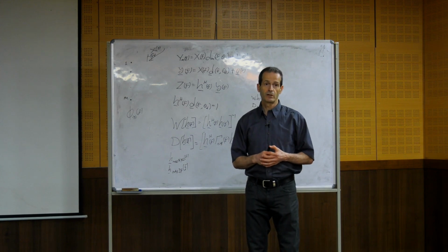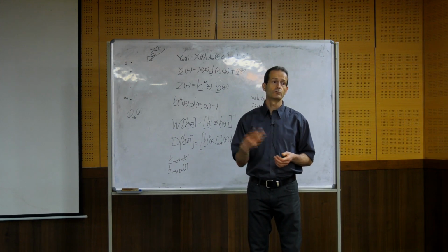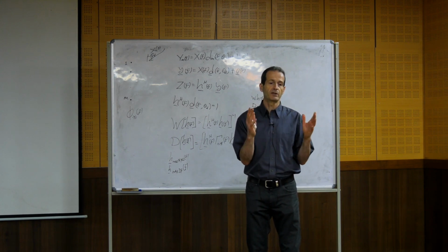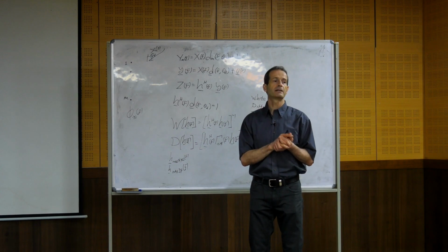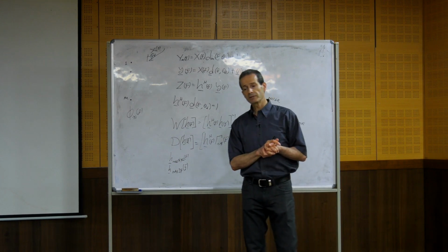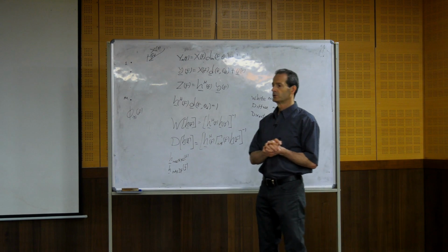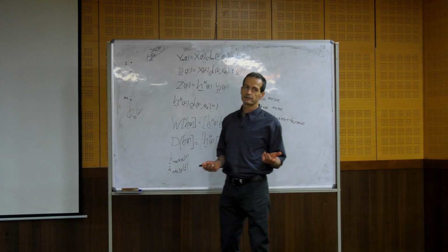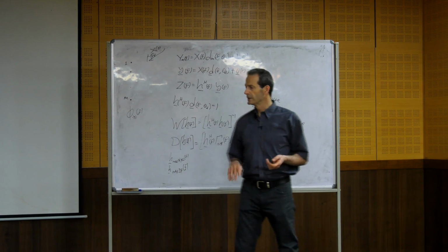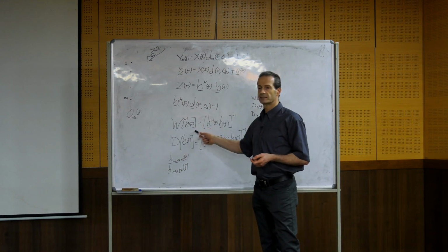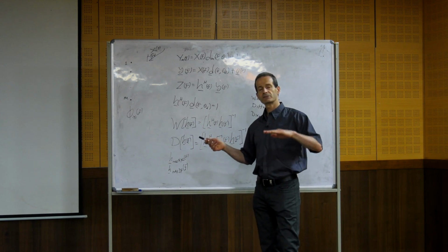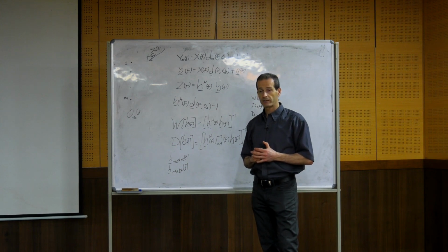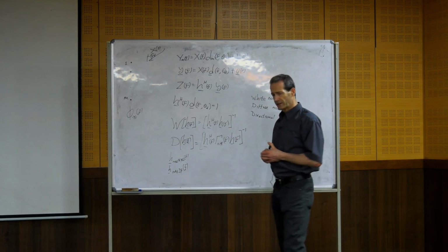Okay? So sometimes you don't want to make calibration or design for each device, even though the devices may be different. So sometimes what you do is just you assume certain positions, you try to make that as accurate as possible, and then you increase the white noise gain. So it becomes less sensitive to other inaccuracies in practice. Okay, any questions so far?